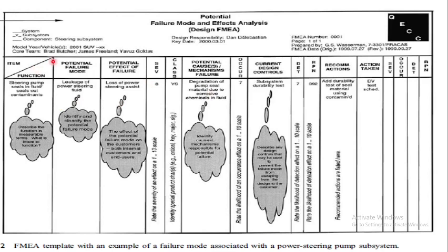Apart from that, I have another example of a steering subsystem. Steering subsystem failure mode and effect analysis, based in the category of DFMEA. If you read it, it will help you. The functions, failure modes given, effect of failure, severity classes, causes of failure, occurrence, detection, RPN calculated, recommended action shown, action taken, and optimized value of RPN being obtained. So this is how you basically perform a failure mode and effect analysis of your system.